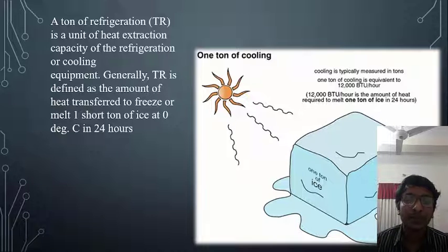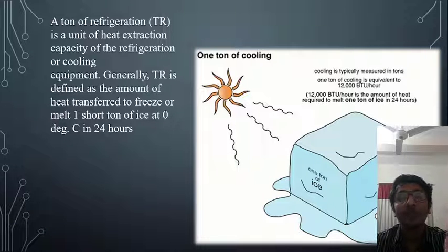And then to make it power in kilowatt, we have to divide it by time and 1000 to make it a kilowatt. The time is 24 hours, which is equivalent to 86,400 seconds.